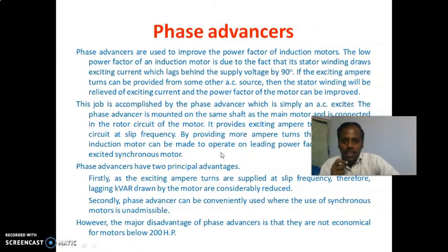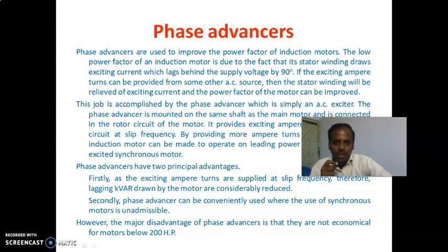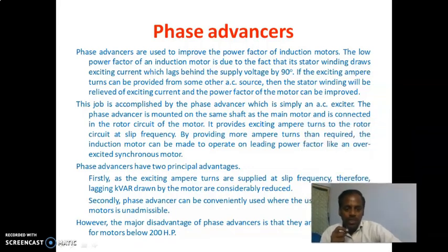The third technique is the phase advancer. Phase advancers are used to improve the power factor of induction motors. The phase advancer is constructed inside the motor.